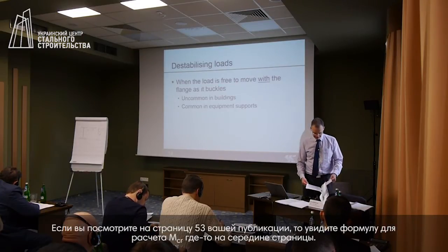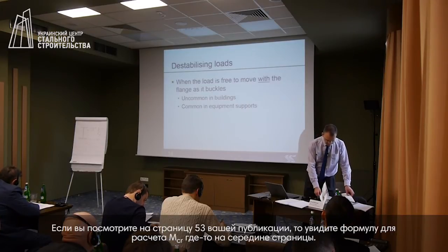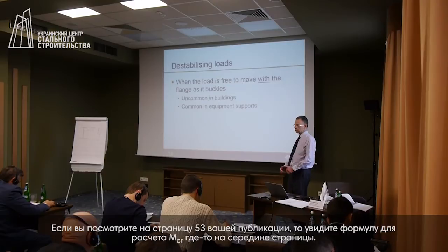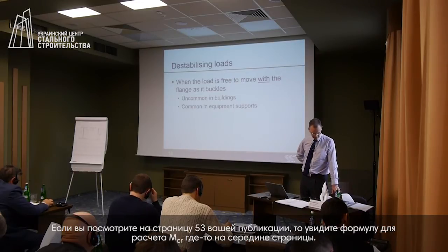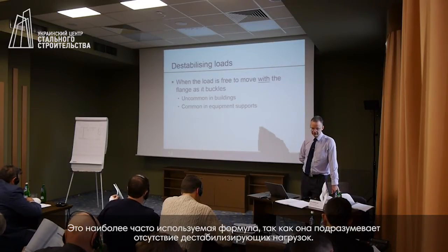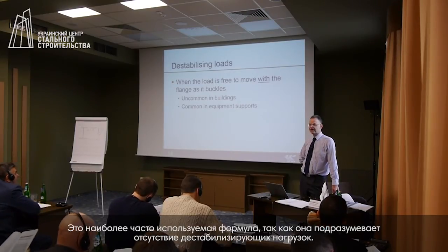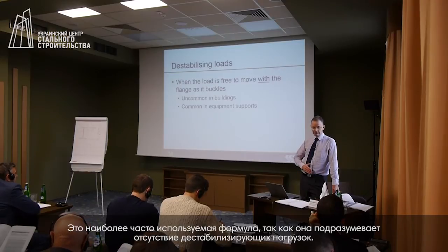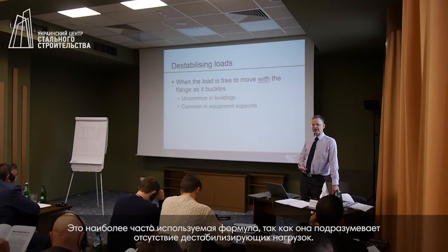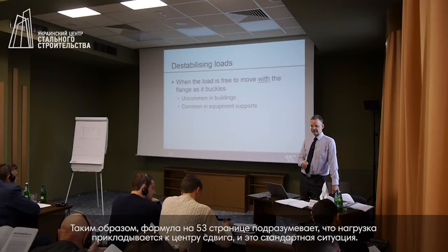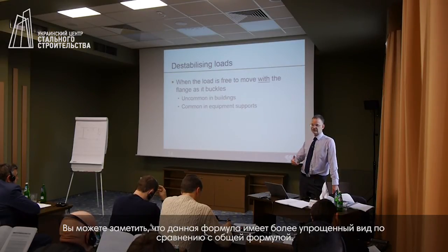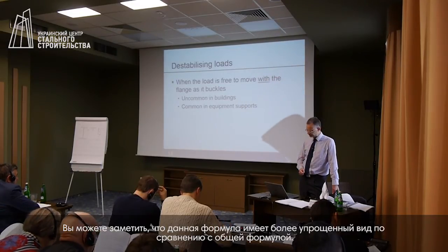If you look on page 53, you have an expression there for M-crit, halfway down the page on page 53. And that would be the expression which is used most of the time, because we do not have to allow for destabilizing loads. So the expression on page 53 assumes that the load is applied at the shear center. And that will be the common situation.